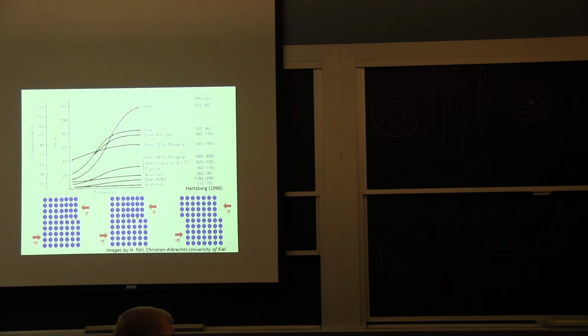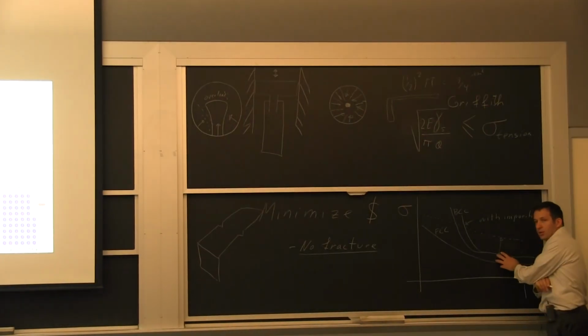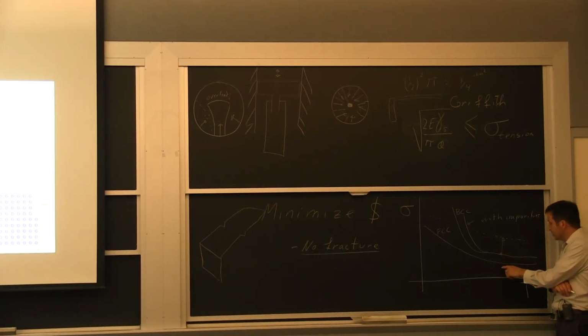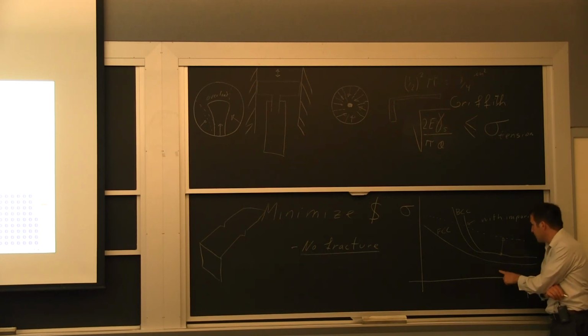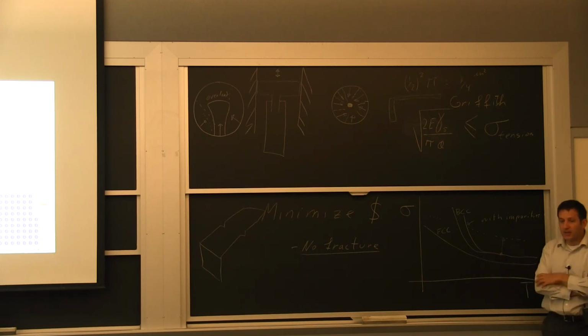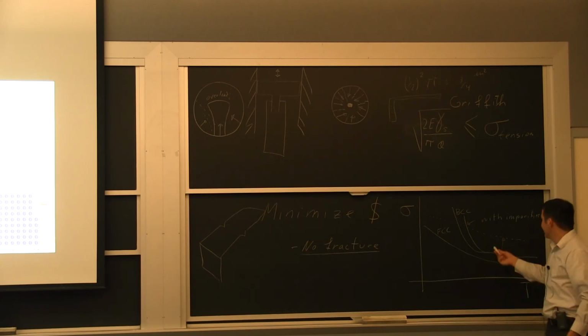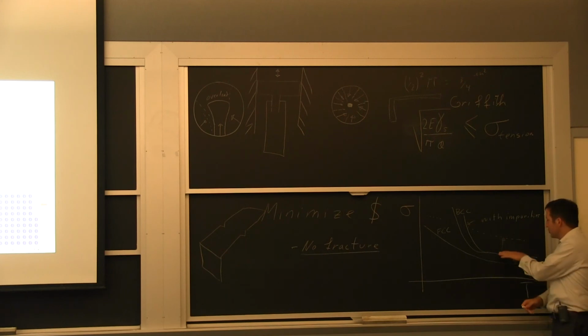Most heat treatments that we do on material will affect this curve. So if I start with a regular structural steel, I'm say right here, very low strength for a given temperature, but I'm going to be able to displace and flow the material a lot before the flow stress becomes high enough to break. If I have a tempered high strength steel, this curve is still the same, but you're starting at a higher point.